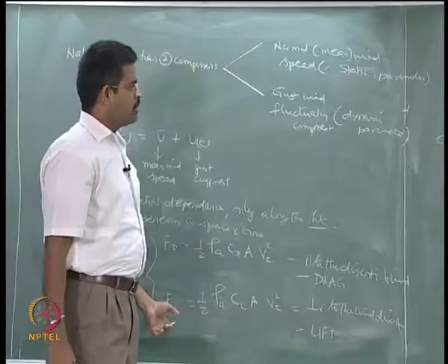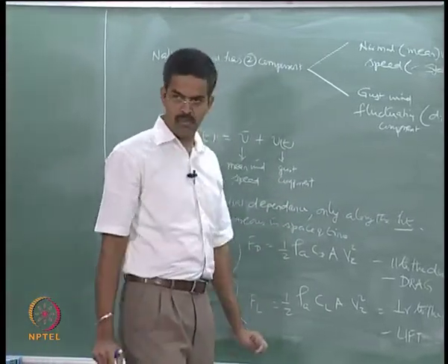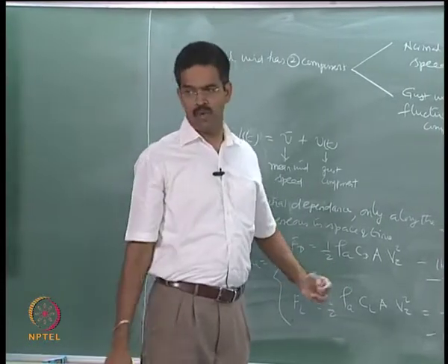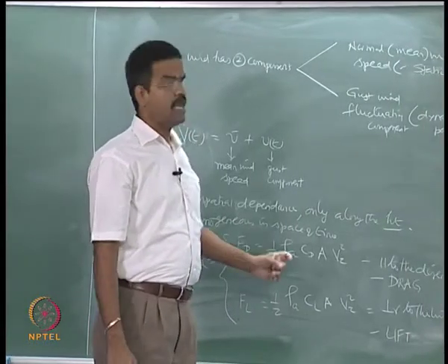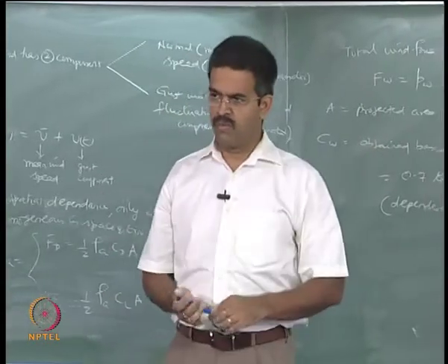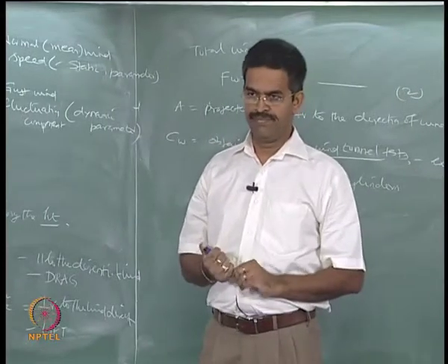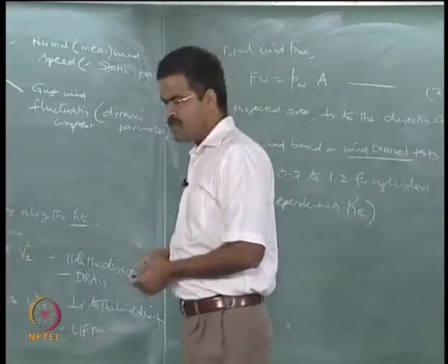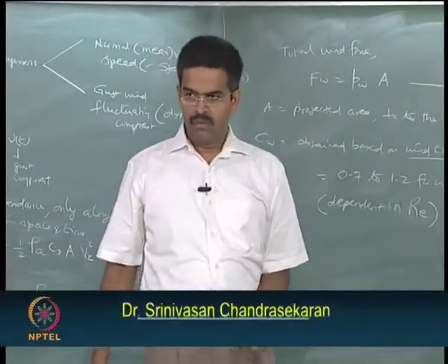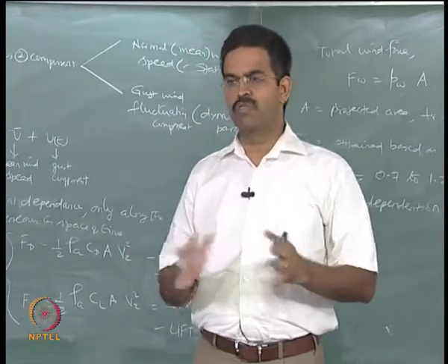So, we stop here now. We will continue in the next lecture with the spectrum which would advise me to compute the wind forces on the members, and how the complexity and randomness of wind loading can be handled in the literature to make it simple for computing the force on members using aerodynamic admittance function. That will be the target, plus we will also discuss the ice load and the earthquake load coming on members of marine structures. Therefore, we will comprehensively discuss the environmental loads coming on members.